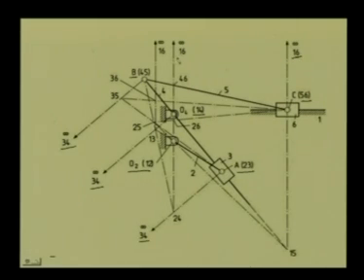That is, on all vertical lines I can say 1, 6 lies at infinity. Following the procedure we just discussed, we locate the rest of the relative instantaneous centers like 1, 3, 2, 4, 1, 5, 4, 6, 3, 5, 3, 6, 2, 5 and 2, 6.